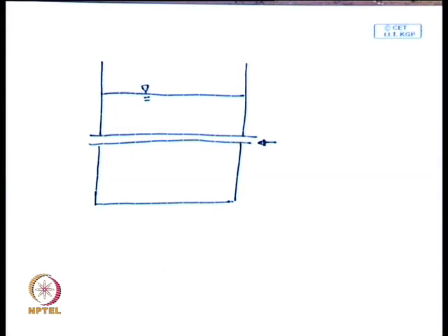So, the saturation temperature of the vapor inside the tube will change. So, by having different pressure you can independently control the heated surface temperature, and that is how you can get a temperature controlled condition for experiment, and the curve which I have shown, the curve drawn in solid black line, that type of pool boiling curve can be generated.